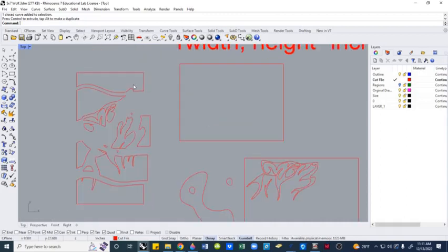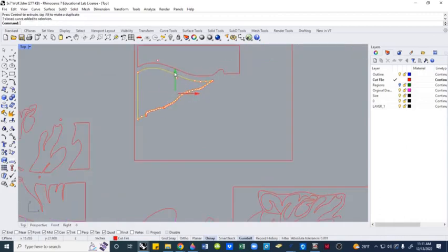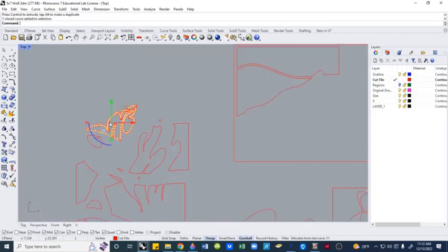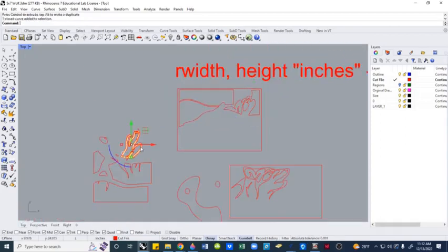Now I'm ready to move this stuff. I'm going to move a couple of these at a time. So I just move this in. I want to get things grouped. Take the time to do this. It reduces our waste and allows us to make our veneer go a lot farther. I typically put in the bigger pieces first and then fill it in with all the little ones. So I'm going to go ahead and do that off screen and bring you back in here in a second.